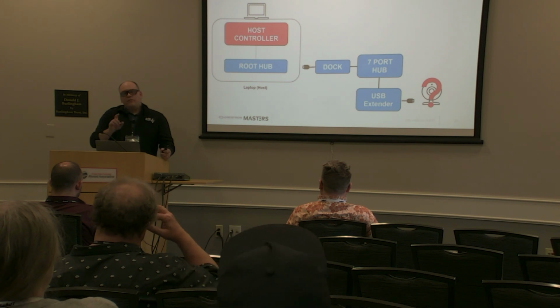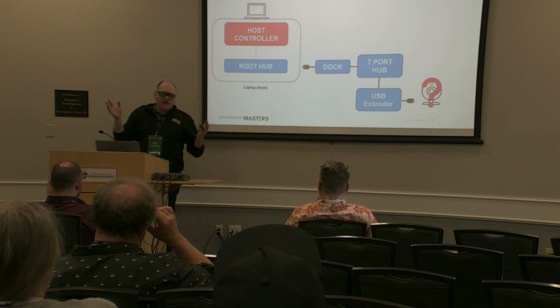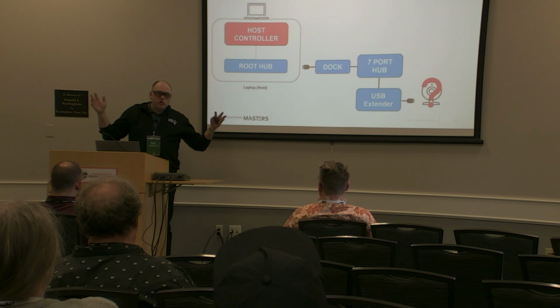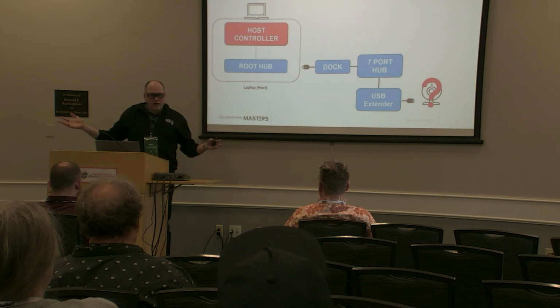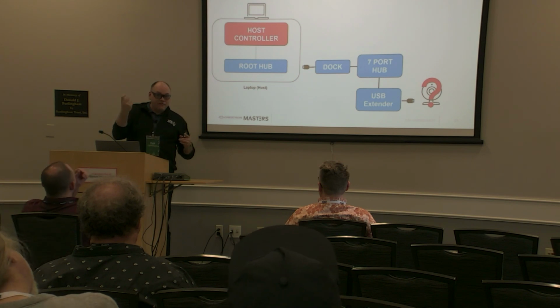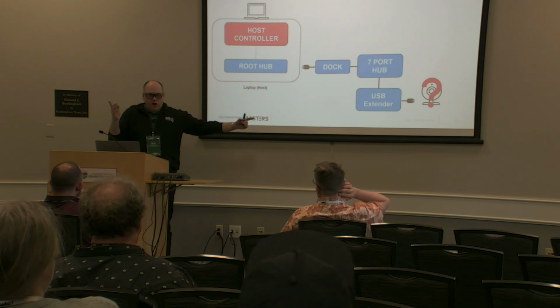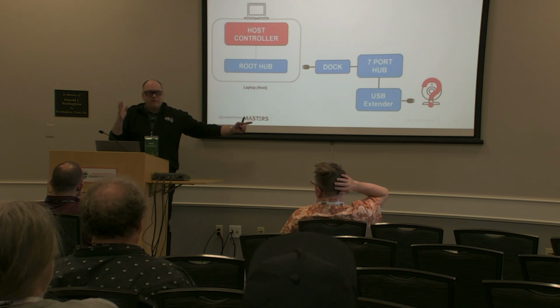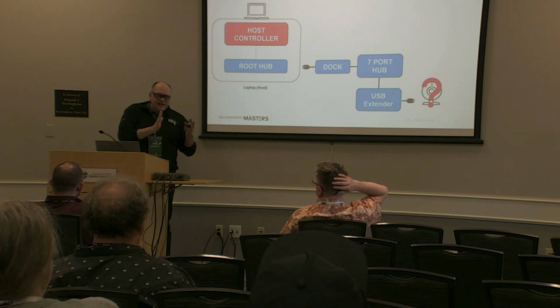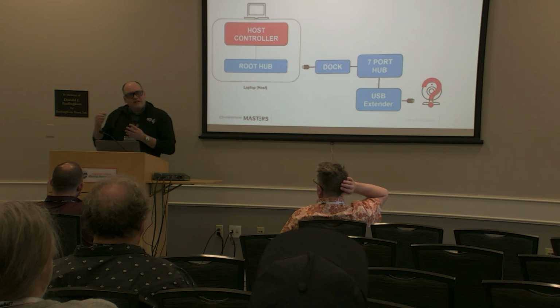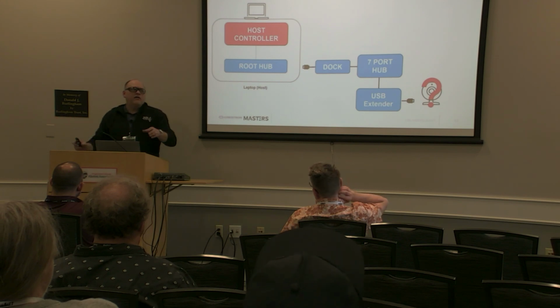Right, but the point is that it won't work. Say you plugged a 20-foot USB cable into the hybrid cable, it's not going to work, right? Because the distance from where it gets clocked at the female end of that cable and the host is too far, the information's not getting there. But when you use the right size cable, it works because it's going to reclock it.